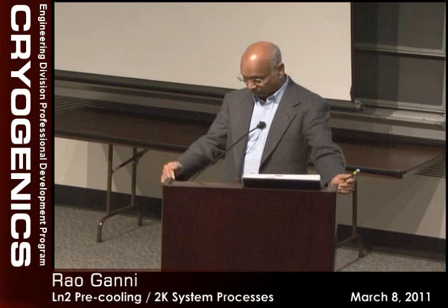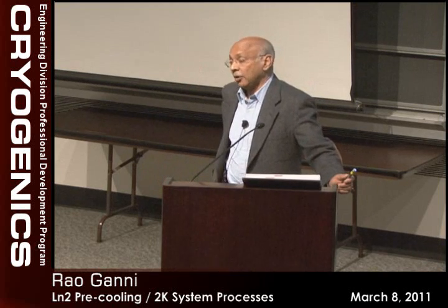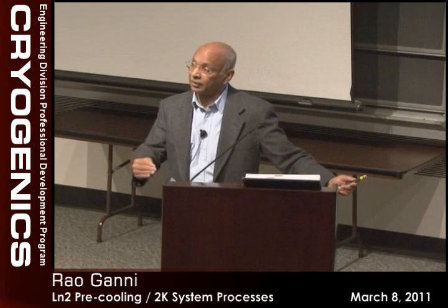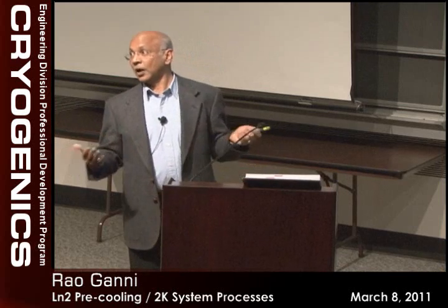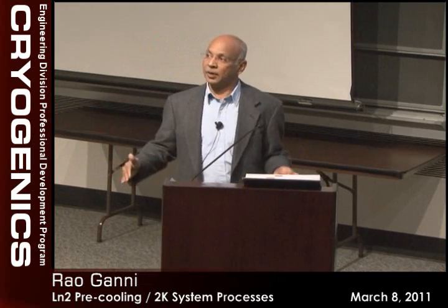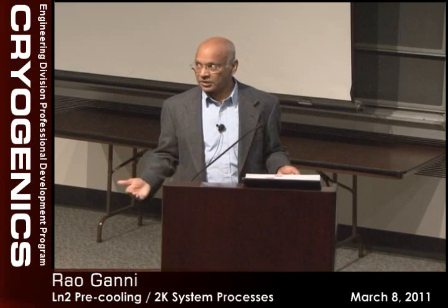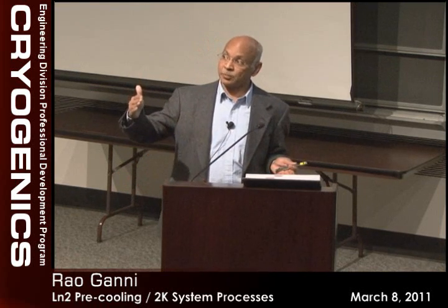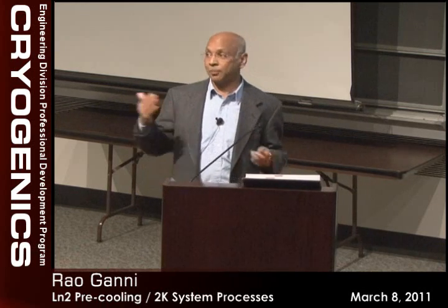And as you keep lowering the temperature, the amount of heat flux you can put in before it changes to boiling will increase exponentially. So that's why we always have this difference, no? People who want to operate say keep pumping down, but for us, taking it down costs you in two ways. One is it reduces the capacity available at the refrigerator. The other is that it increases the pressure ratio, and the reliability and other things come down with it. So you are paying a price.